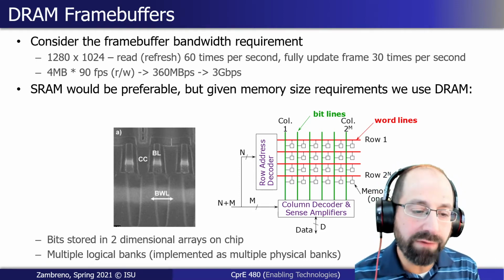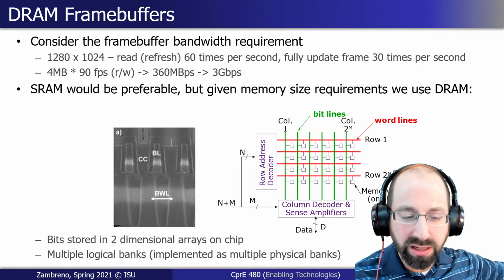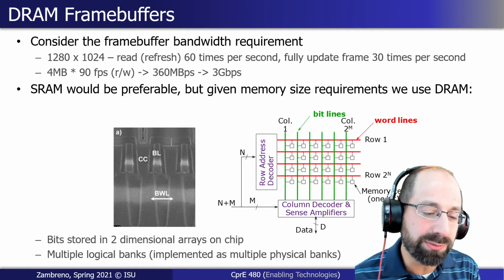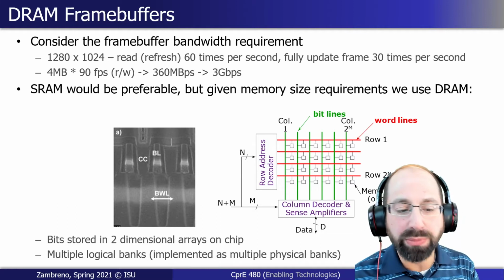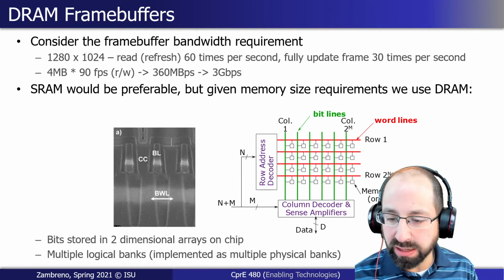So in modern graphics processors, what you'll see is even having what we would consider a relatively Spartan amount of SRAM cache on the device, that number is creeping upwards, but it's still a relatively small amount. You can still get extremely good cache performance out of it because there's just a very regular, reliable memory access pattern. That's just a fundamental feature of doing graphics processing.